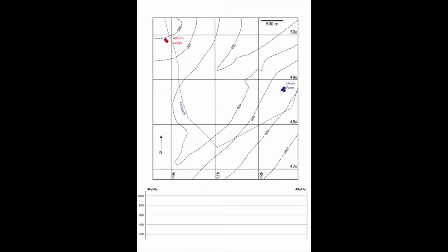So you have these questions to answer, and then this rudimentary topographic map that has a couple of buildings on it. It has ground contours showing you the height of the ground, and it's got a footpath and a north arrow and a scale alongside a grid, which should have all of the components you need to understand where you are on a map. And then this thing at the bottom, we'll use this to construct a hill profile, which is the first step in drawing a cross-section.